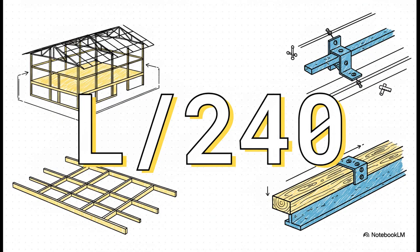And speaking of stiffness, welcome to the world of serviceability. See, in PDD, it's not just about strength, it's about performance. Is the roof going to feel bouncy when someone walks on it? Is it going to sag and create puddles of water? L over 240 is a super common deflection limit for roofs. And a lot of the time, this number, which is all about controlling sag, is what will actually govern your purlin selection, not just its ultimate strength.